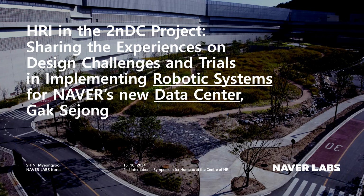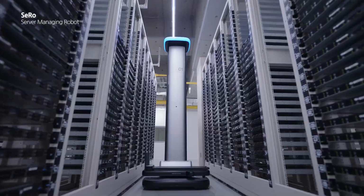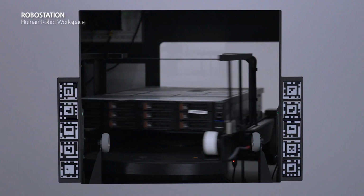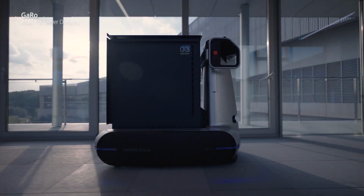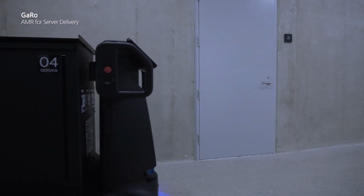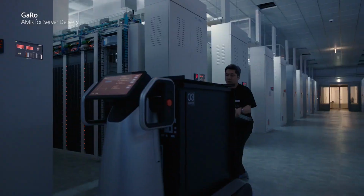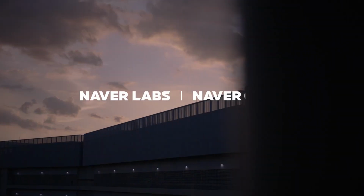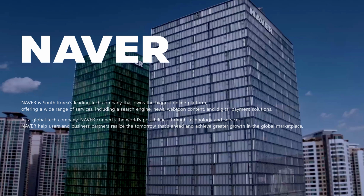Yesterday, as Martin introduced, 1784 is the name of NAVER's second headquarters. It is the world's first robot-friendly building, and it specifically has robot-only elevators, centrally controlled doors and elevators, flat floors without thresholds for robot movement, building finishes that support the visual localization and LiDAR of the robot, and desk layouts for a smooth robot path.